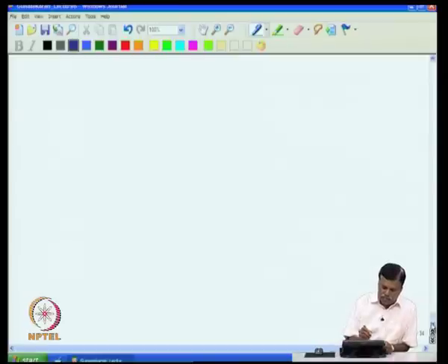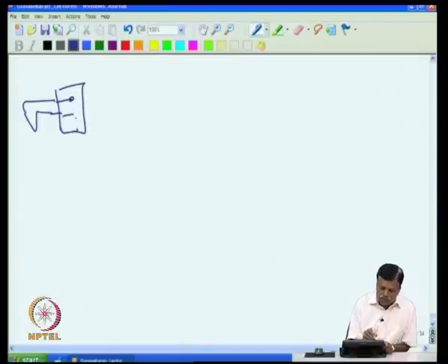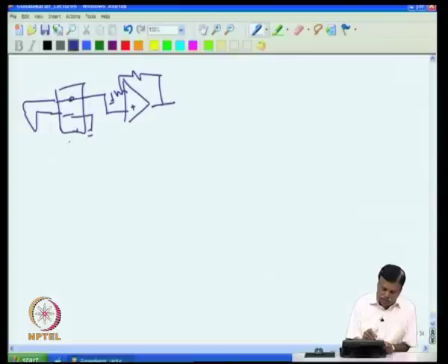So now if I see the whole circuit, it looks like this. If I draw it, I take this, then I put the block to terminate the junction, then I put the amplifier here to amplify the thermocouple voltage. Then we measure the temperature of this block by putting minus 15 volt. Then we take this, then we have put the ambient temperature compensation circuit.